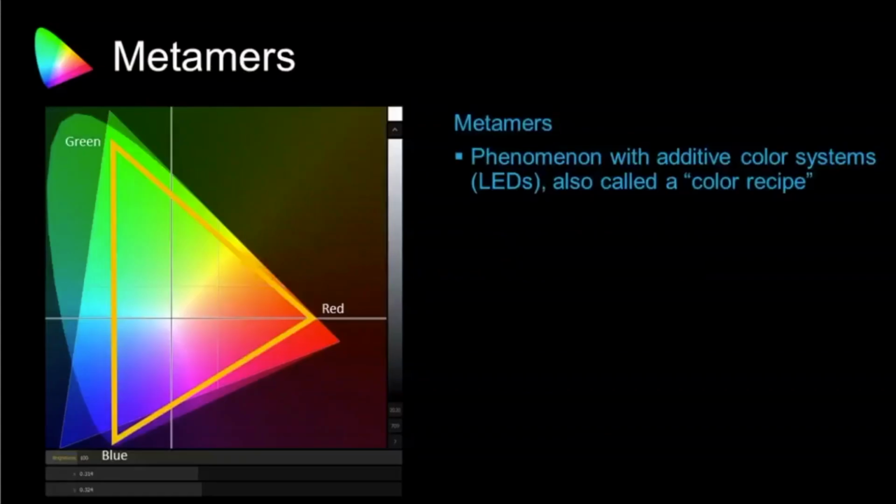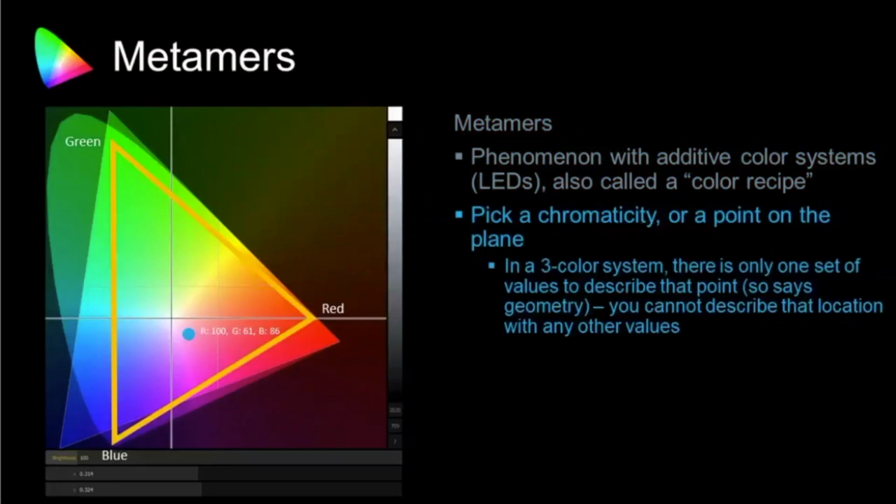What are metamers? Metamers are a phenomenon, particularly with additive color systems, LEDs, in entertainment lighting, that we call a color recipe, right? And it's basically the ability to have the same chromaticity, the same XYZ component, with multiple ways to get to that same location.